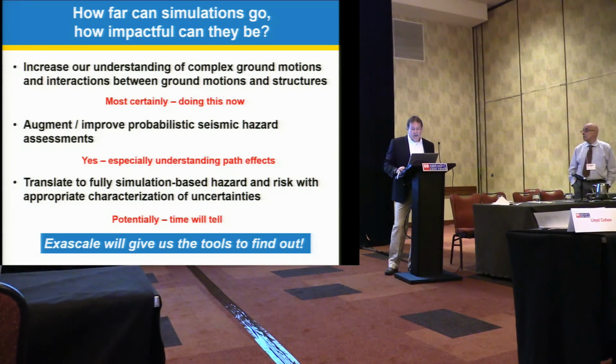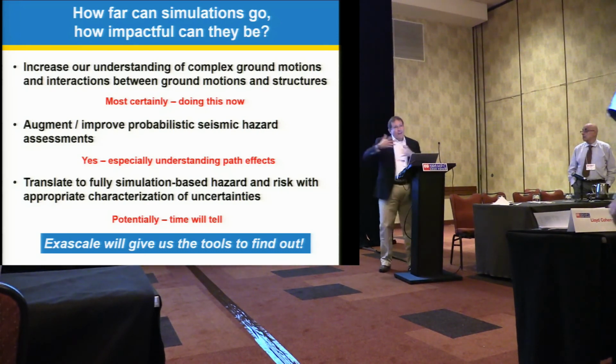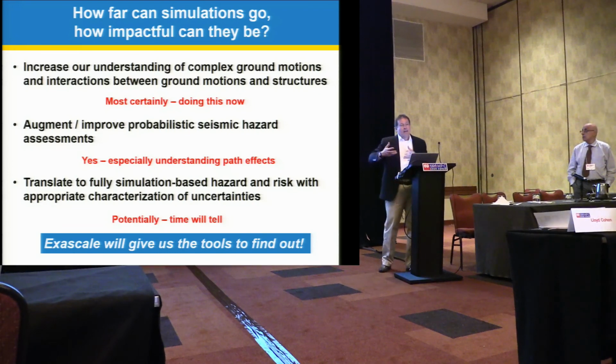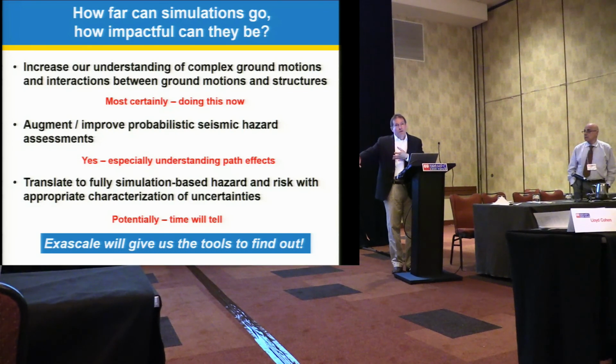You've assumed that structure use a linear elastic model. And in point of fact, the essence of performance-based design is if that structure becomes damaged in some context, that may not be bad. It may be a mechanism for dissipating energy as long as it doesn't exceed a performance goal you have and fall down or become too damaged.